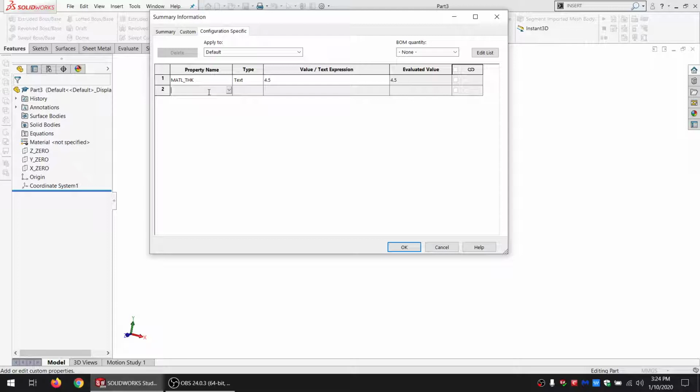I'm also going to make a line called Kerf. Kerf is basically what you lose when you laser cut. So you're cutting some material away between two pieces, and it's basically the width of the laser beam as it cuts through the material. And I happen to already know through experimentation that on my machine with this material, I get a kerf of 0.11 millimeters.